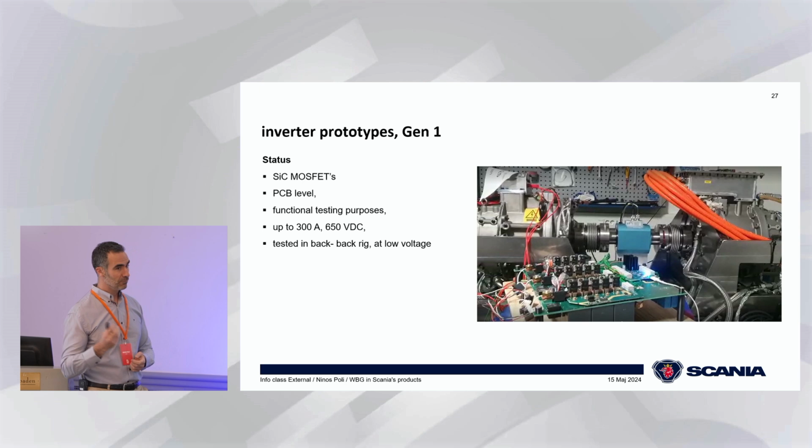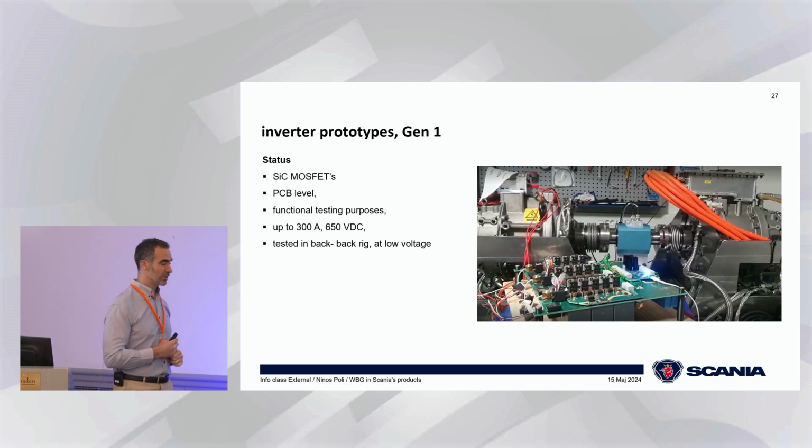So that's why we have some research activities ongoing. We have built a couple of prototype inverters. I will show the first one here. This one is based on silicon carbide MOSFETs. It's on a PCB level, so it's a bit simpler. We have performed functional testing in the lab in a back-to-back rig at Scania at lower voltage levels and power levels.